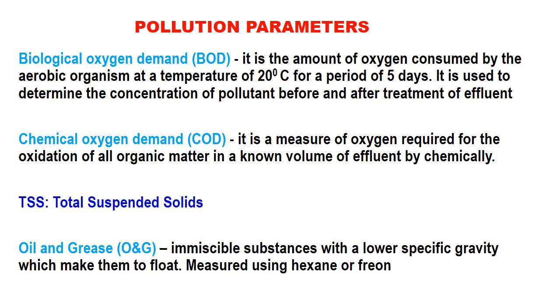Similarly, there is another one called chemical oxygen demand. Here it is done chemically, and we measure how much oxygen is required to decompose the pollutant. Then there is another important parameter called TSS, that is the total suspended solids. These are solids which neither settle at the bottom nor float on the surface. Such materials which remain inside the water, neither settling nor floating, are called total suspended solids. Similarly, there is another one, that is oil and grease content. These are immiscible substances with a lower specific gravity which make them float, measured using hexane or freon.